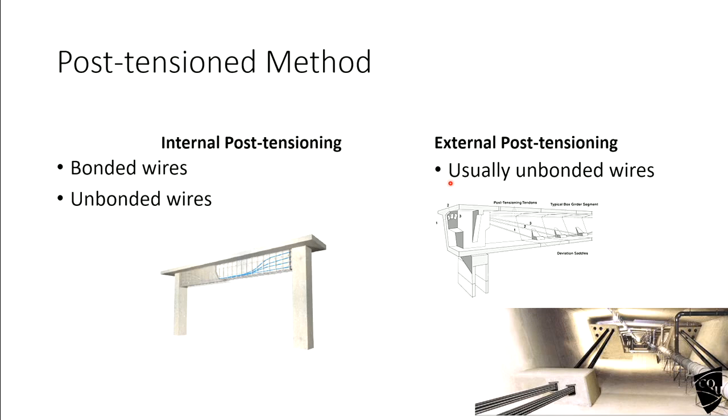So if I ask you to design a pre-stressed beam, technically you should be able to tell me the size or depth of the beam, as you did in the RC, and you should be able to tell me the amount of compressive force you want to apply, because here we apply compressive force, not the steel bars. We put the steel bars to apply compressive force. So you should be able to tell me how much compressive force I should apply and where to apply.